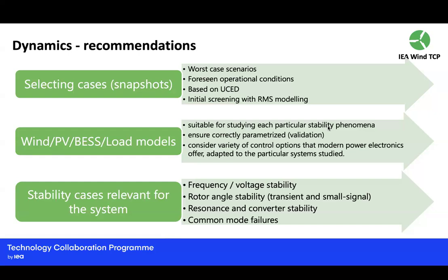You can translate it into: I need so many synchronous generators committed in a unit commitment model all the time. At any given time, I cannot let less than this amount of synchronous generation online. But this kind of breaks, because now there are ways to do it even with inverter-based resources. So the question becomes, how do you feed it back? Not only do you need to put in a constraint, you need to put in capabilities that before you were not looking at in unit commitment.